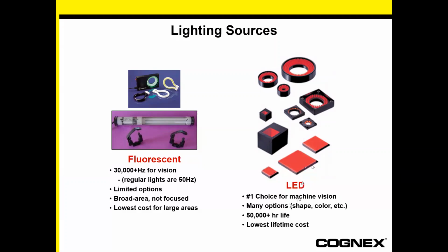Doing OCR applications, we use a lot of red light. We're using a specific bandwidth so that we can have sharper characters. So it all comes back to the application that we're looking at and what we need to do. We can use light at the UV spectrum to highlight whiter products, or maybe we have done UV printing on some applications and then we use UV light to make it stand out so we can do an OCR, read a code that's being printed.